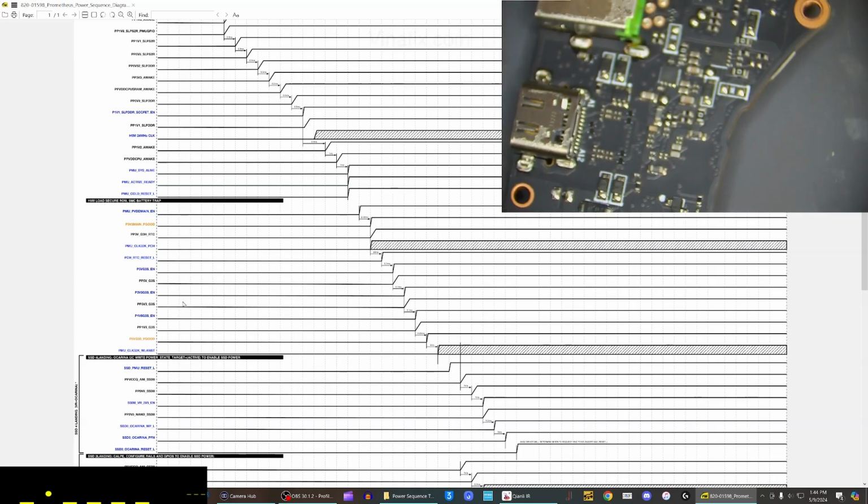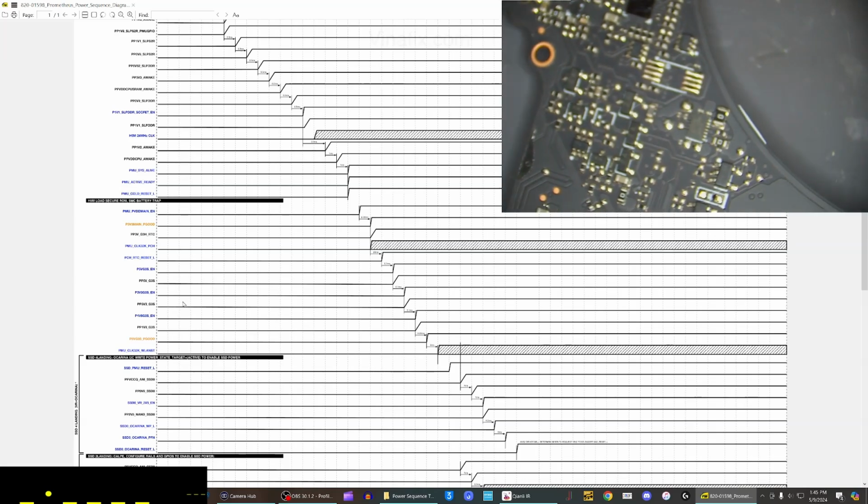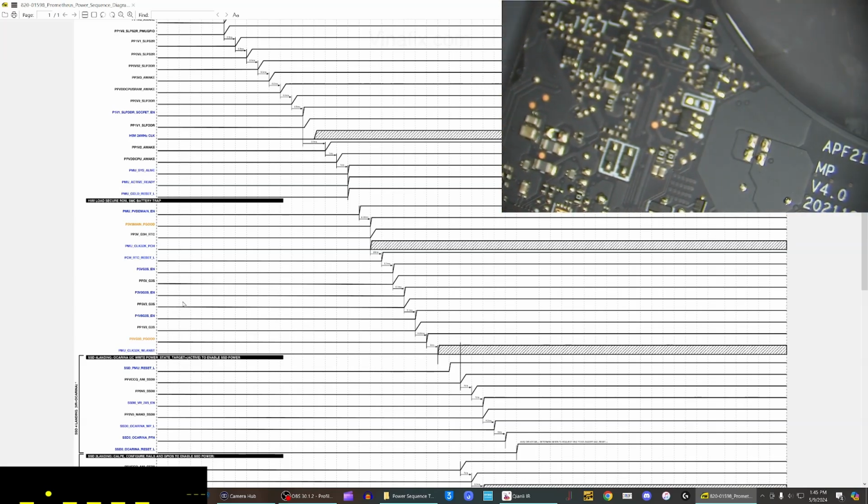We already visually inspected the board. I don't see anything. No, the ports look bad. Nothing. No hints. I just plugged in power and started probing around voltages on fuses, pretty much. I checked for shorts in a few key areas. I started looking around this area.